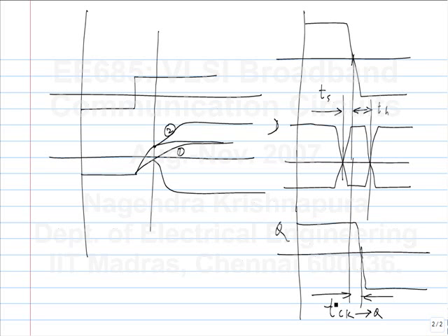But why might that change in the hold phase? Yeah, it takes time for the current to steer from one side to the other. Firstly, the rise time of the clock will be non-zero, and the switching voltage of the differential pair is also non-zero. So both the rise time and the switching voltage are not zero, right?